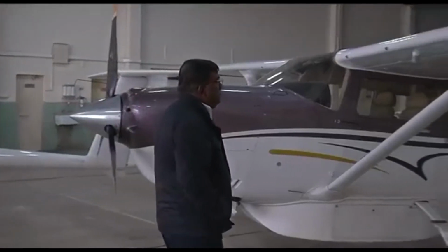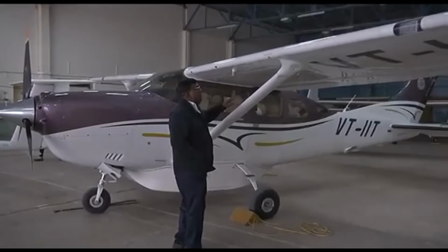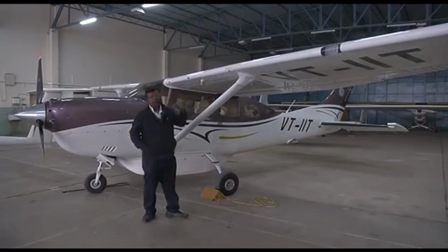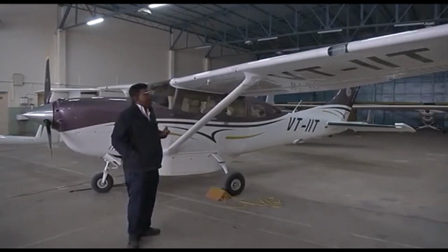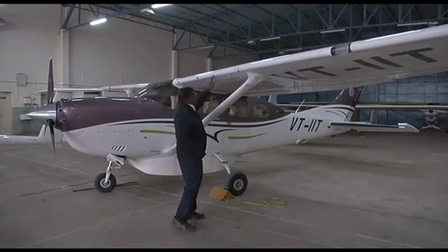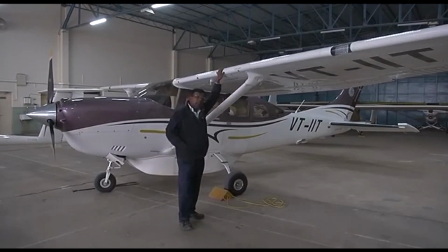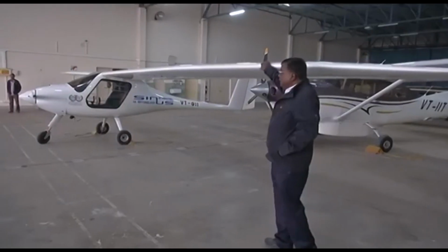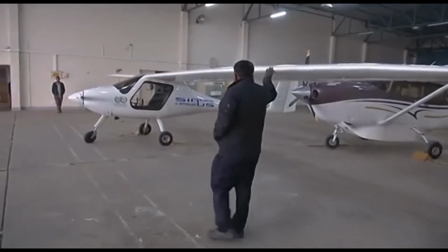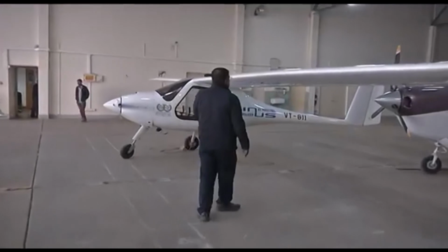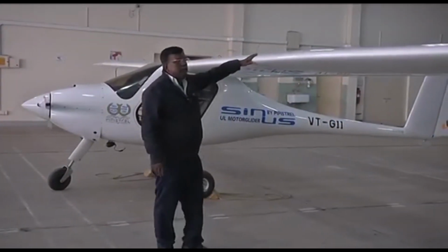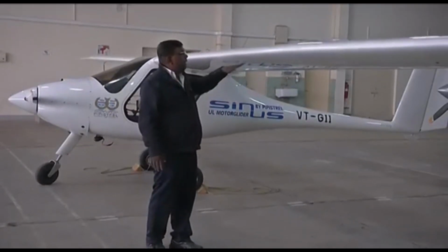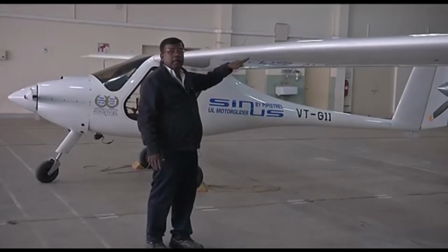We were discussing stability for long, and we were very emphatic that the wing's primary role is for lift, but we'll see in a secondary manner, the wing also supports stability or it may contribute to static instability. This is Sinus 912. This is also a high wing aircraft. Now when I am talking about static stability, suppose this airplane was flying at an angle of 1 or 2 degrees, and there is an upward gust and an additional angle of attack is coming like this as a disturbance.